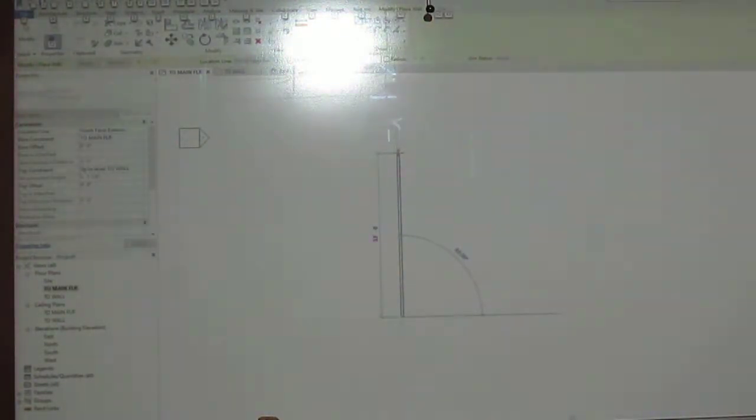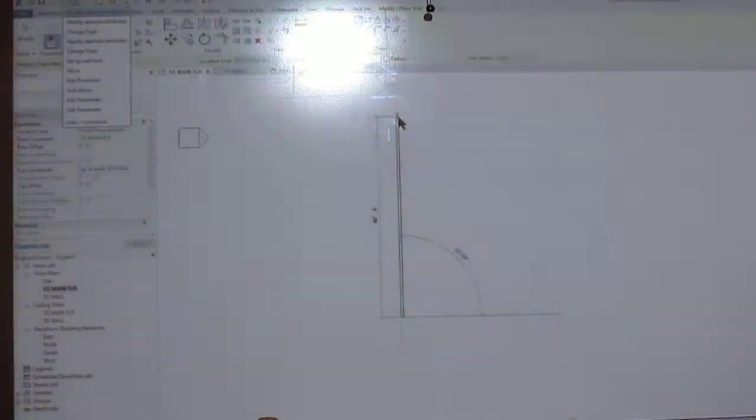One of these locks you in. Shift. Oh, Shift key. Shift key locks you in, vertical or horizontal. So all we're going to do is come straight up, hold yourself in, and type in the total distance. So what's our total distance here? 48 feet? So I'm going to hit 48.